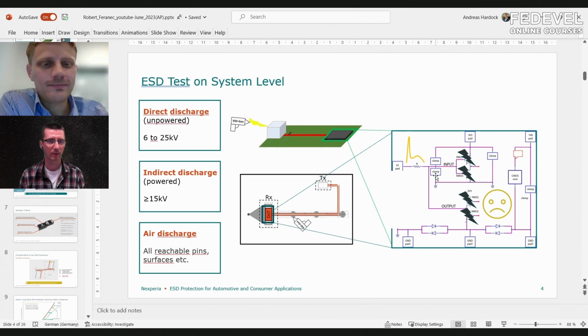I would like to point out, a number of people told me that if there is ESD damage, it doesn't necessarily mean a transistor or something inside the chip will be completely damaged. It may work somehow, or work for some time and then be damaged, but much sooner than would be expected. So even if there is no visible ESD damage, it doesn't mean there was no damage. Yes, this is a very good point.